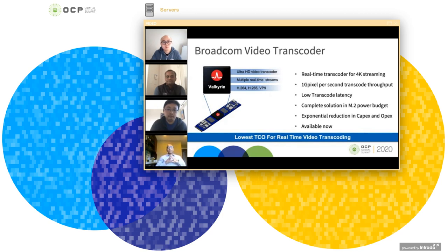As Bharat mentioned, Broadcom has been working with Facebook to develop a high-density real-time video transcoder ASIC. This video transcoder ASIC supports multiple codecs. It supports all the widely used codecs like H.264, H.265, VP9. It has a very high transcode throughput of 1 gigapixel per second. And this 1 gigapixel per second throughput can be subdivided into multiple video streams of lower resolutions, all the way up to 4K resolution.